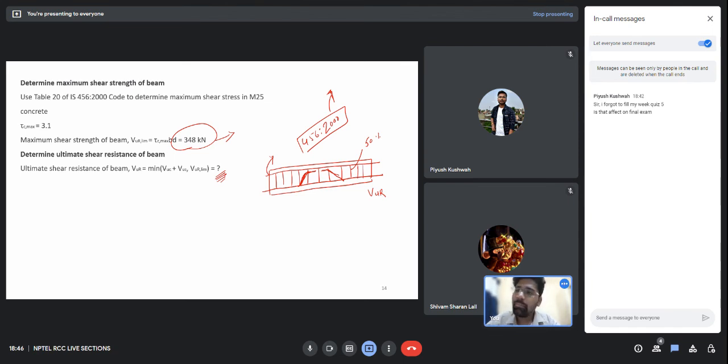But it's true that many people use high grade, because what generally happens on the construction side is that the procurement is done for a similar grade of steel for the longitudinal bars as well as for the stirrups. So they do not take the headache to provide different grades of steel for stirrups and different grades for longitudinal bars. They like to avoid that, but those are all things we should control as design engineers.